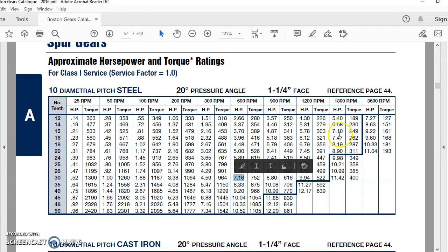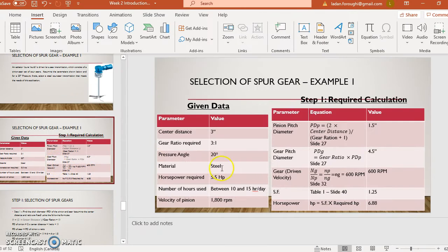I could just save more energy here. 710, 716, these are close, and our gear ratio would be 2 to 1. If a client asks me to do this, I will do it for him with 15 and 45, but I'm going to recommend to them that 2 to 1 would also work for you with 30 instead of 45. That means you are going to save energy, save money, everything. So we satisfy 3 to 1.